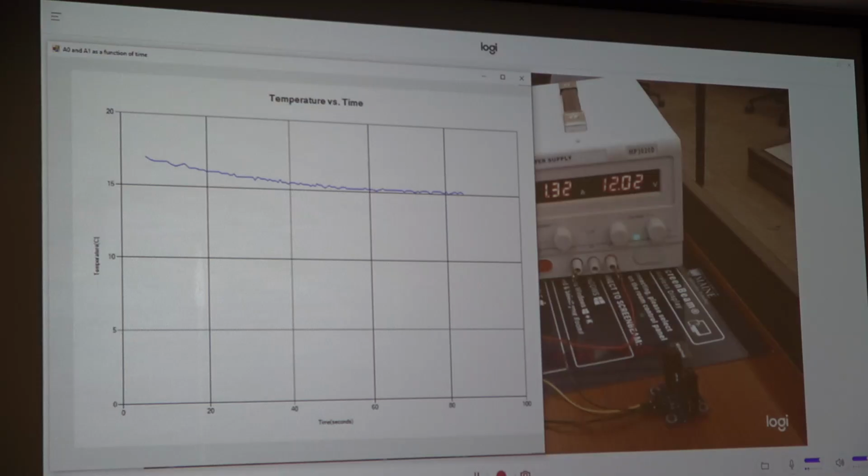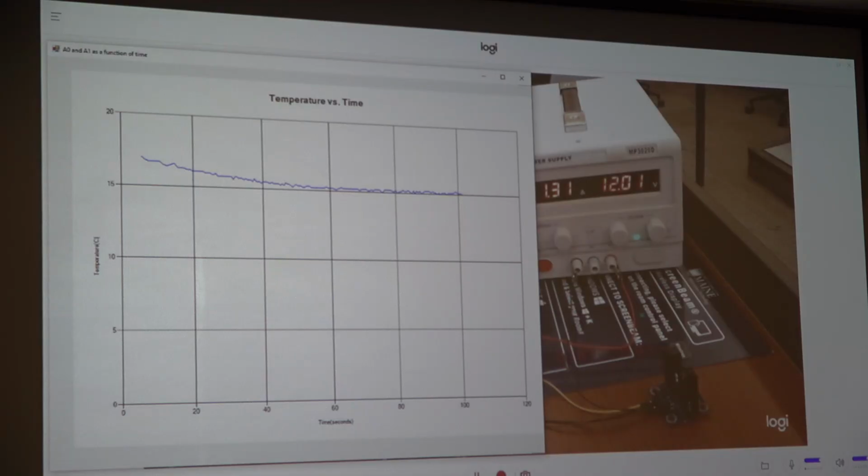As you can see, we're starting to flatten out. We're not really dropping a whole lot anymore. It still wants to get to 10C, but we might die of old age before we get there. Actually, we're not getting there. Okay. So there you go. Proportional. It just doesn't get you to set point.